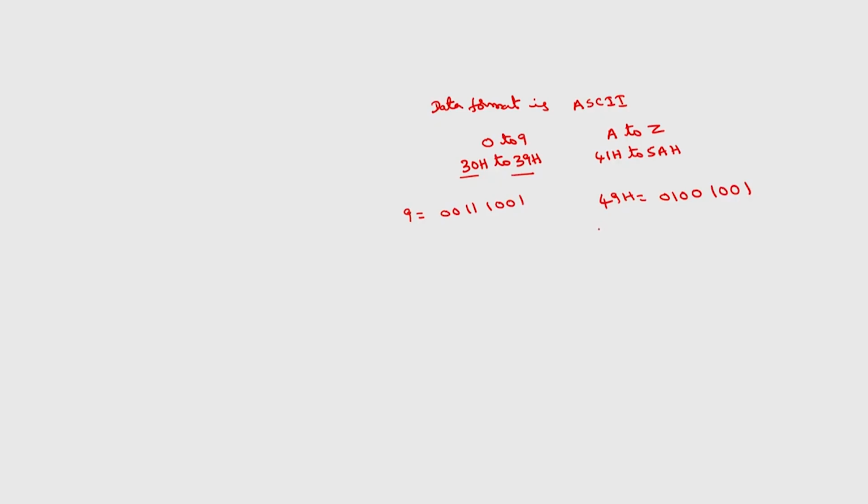serial interface, the standards. I want to use one stop bit. Number of start bits is equal to 1. So, number of start bits I want to take 1 and number of stop bits I want to take 2. So, start bit will normally be space and stop bit will be represented by mark.